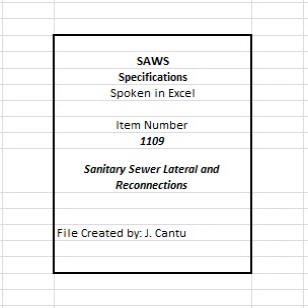For parallel and replacement sewers, service connections may be located as pipe laying progresses from the downstream to the upstream direction. C. Properly disconnect existing connections from the sewer main and reconnect to the rehabilitated section of main, as described in this section. D. Reconnect service connections, including those that go to unoccupied or abandoned buildings or to vacant lots, unless directed otherwise by the inspector.